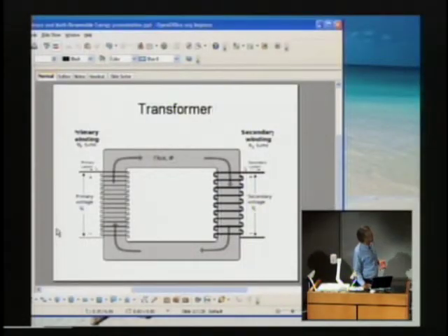This is a diagram of a simple single-phase transformer. That's just 2 wires going in with alternating current and 2 wires going out. Now, because the current is always changing, it produces a changing magnetic field, and that cuts across the windings on the other side. The magnetic flux is concentrated by the core, which is usually an iron core in this case.